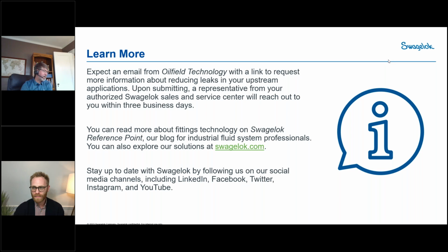Sure, a very popular way to create a nice seal is to put grease on it. A lot of valve manufacturers do that, and it's a good way to clog up that continuous pore structure. The problem with doing that, though, especially with a fitting, is that grease will continually wear away.